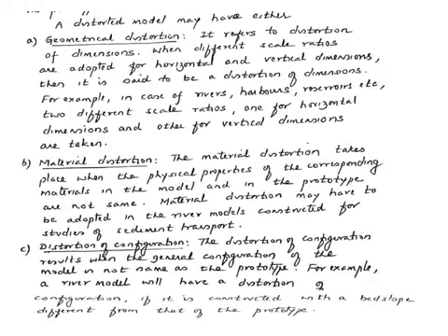Sometimes we have material distortions, where the physical properties of the corresponding materials in the model and prototype are not the same. For river models, we can construct them with different materials in the laboratory. This is particularly useful for studies of sediment transport. So when we distort the material, it is called material distortion.